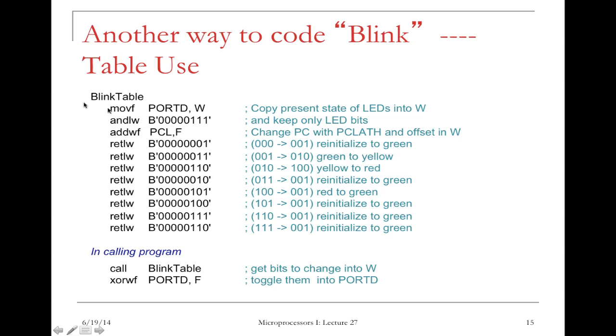This is the entry point of the subroutine. And as you can see, it has a lot of different RETLW instructions. RETLW instruction will return from subroutine. Also, before it returns, it will put this value to the working register, then return. Okay, so this RETLW actually does two things. Put this value into the working register, then return from the subroutine.